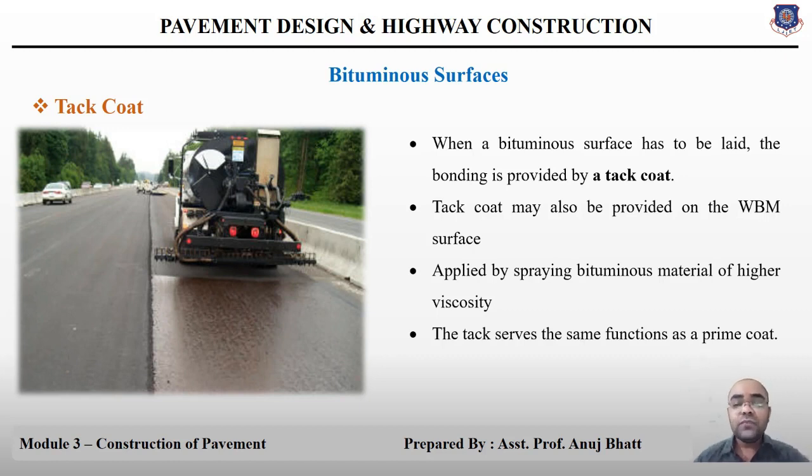Yes, so this is how we can apply the tack coat. There is no difficult or tedious procedure for this. It is a simple procedure. First you have to make that surface smooth, or level we can say. Then you apply the bituminous material at some rate, and then you have to keep it to cure for a few days. So this is the simple procedure of applying the tack coat and the prime coat.